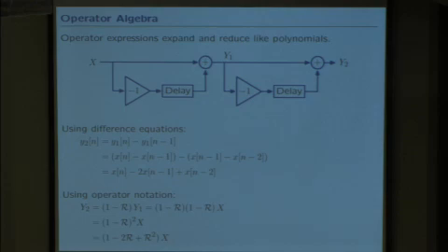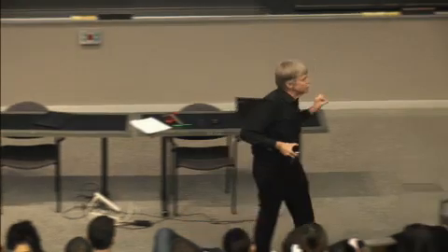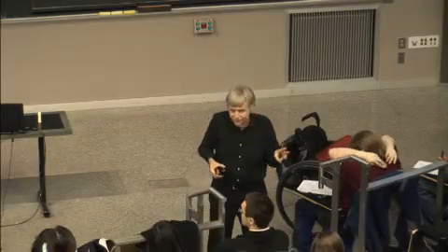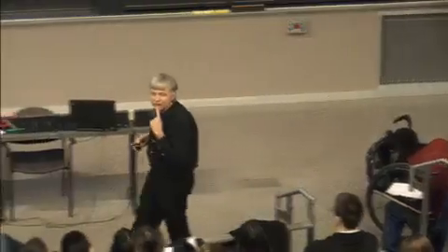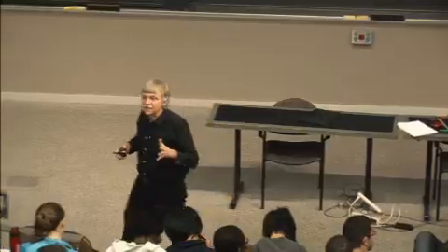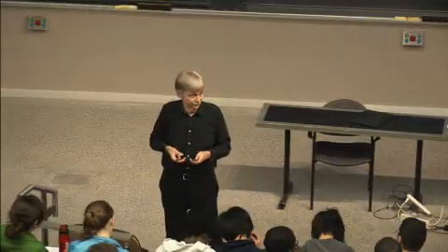The point is, the operator notation is just as compact as the difference equation representation, and it contains all the information that's in block diagrams, and it's just as easy to manipulate as a polynomial. So it's got lots of features that make it superior to difference equations.